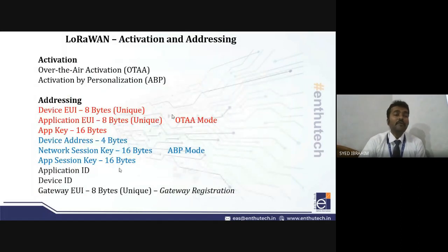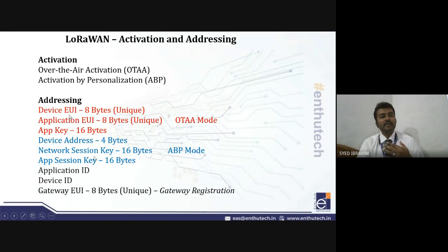And now from the cloud we'll be using all these three pieces of information if we are going for this over the air activation method. So the device EUI, the device extended unique identifier, and similarly the application EUI and the application key.